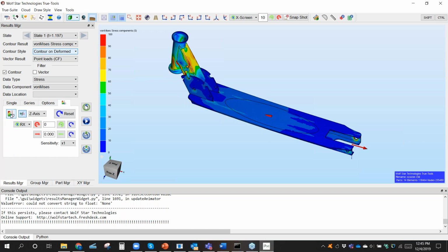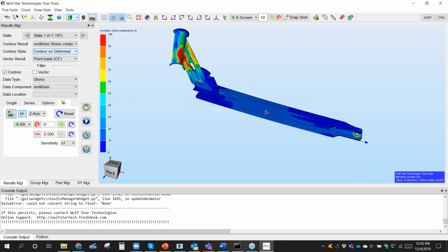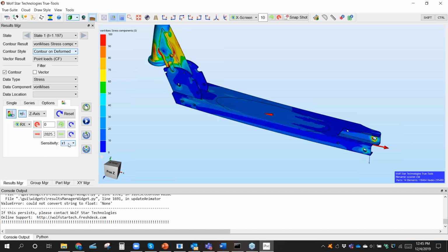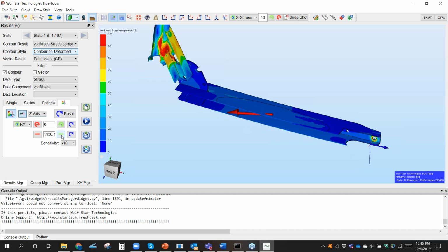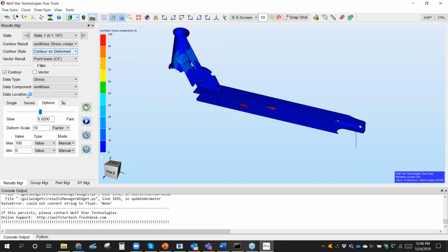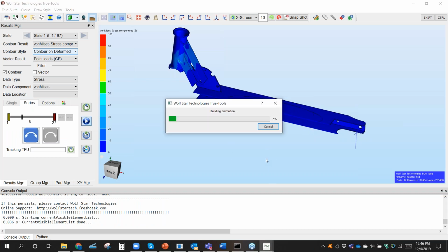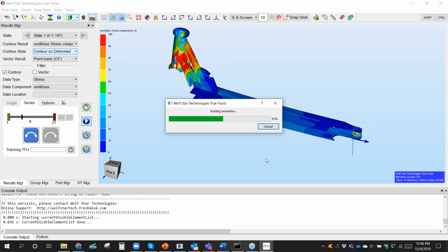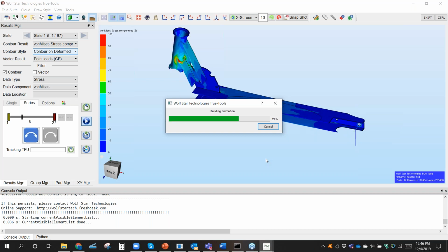I'm going to put a section cut on the part here. We'll just push it back a little bit just so we can see our vector. I want to have it look nice, and also let's set our factor of 10, which will be good. Okay, here we go. So now we've got an operating deflection shape on our Razor scooter just from laying 12 strain gauges. So not too bad.